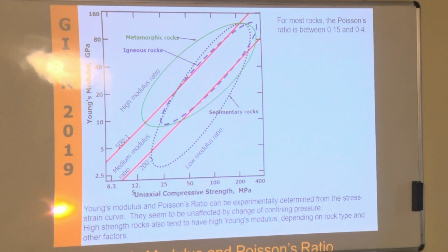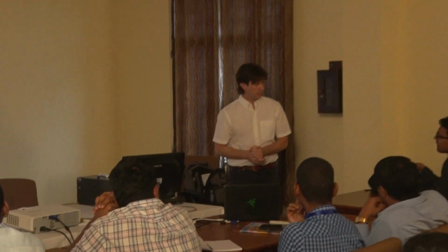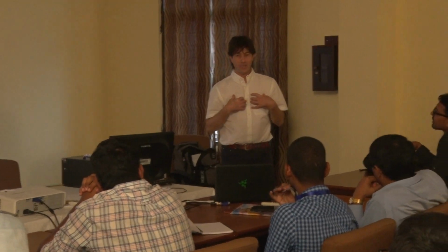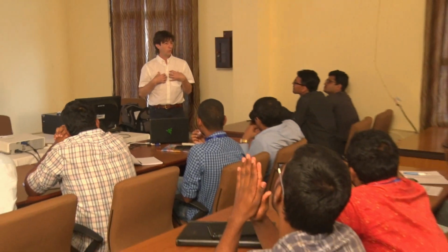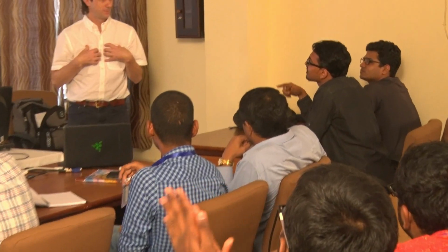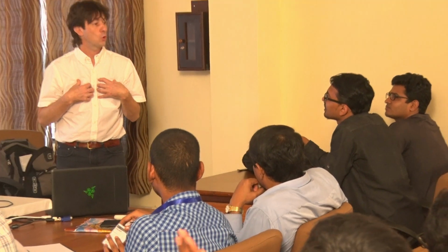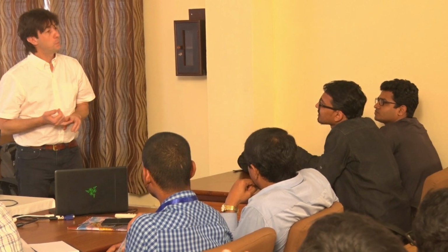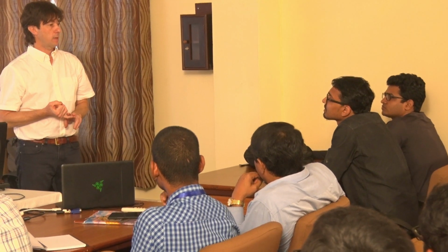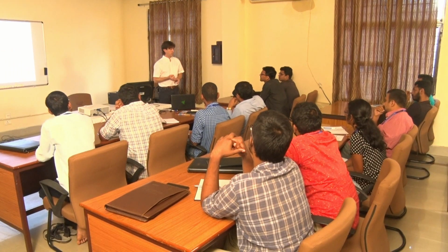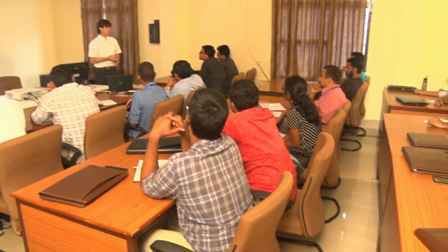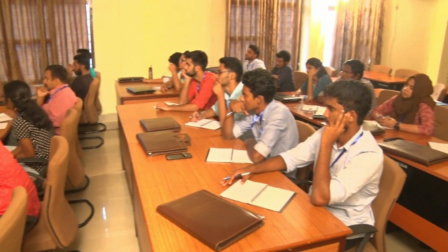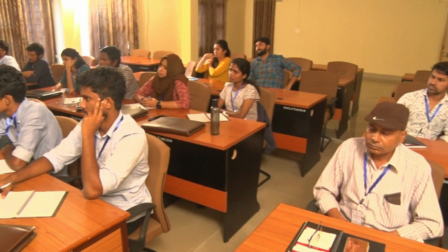Yes, there is an accuracy on this curve. The radial strain, on all the samples I saw, yes. So why is it so? Why is the axial strain linear and why is the lateral strain not? Good question. And my take is there are several reasons. One is, for example, the anisotropy in your material. The second is the heterogeneity of your material.